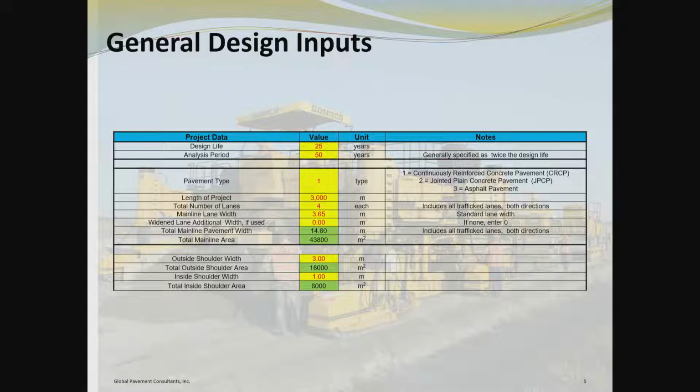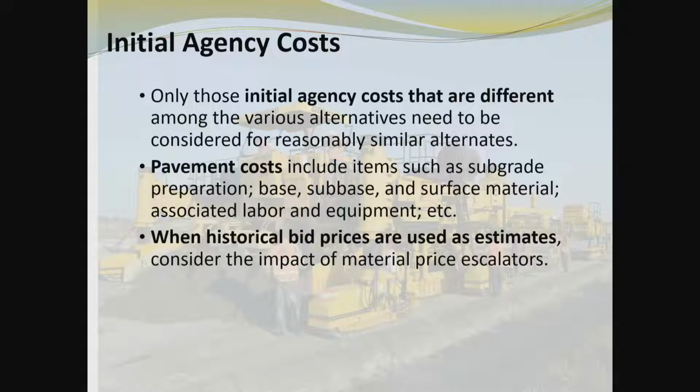let's say 30 centimeters thick, you probably won't fail that by fatigue. If you take a 30 centimeter full depth asphalt pavement, you very could deteriorate that pavement based on loads through rutting and through shoving and some different types of asphalt related distresses. So what's an equivalent design? It's not 30 centimeters. It's not a direct one-to-one comparison. It ought to be based on load carrying capacity to a specific point of deterioration. But that's kind of getting in the weeds for the topic we're discussing.